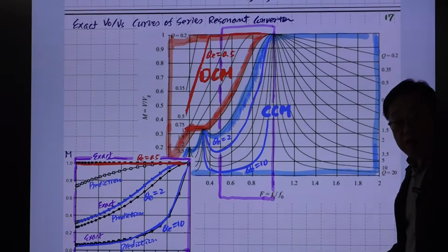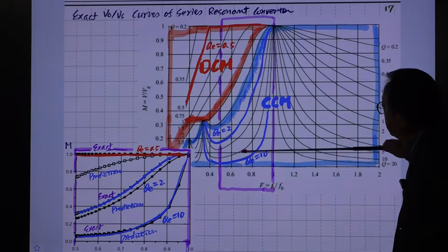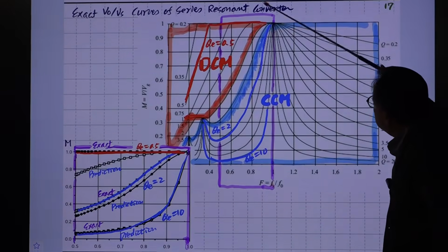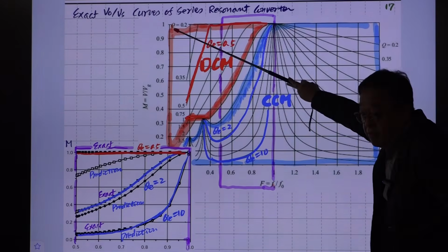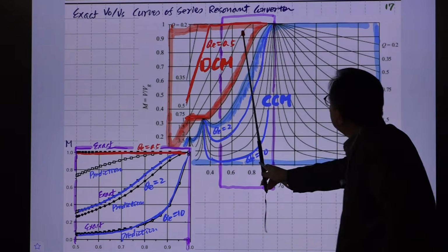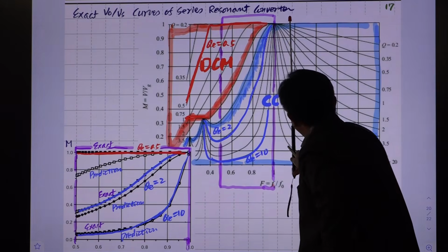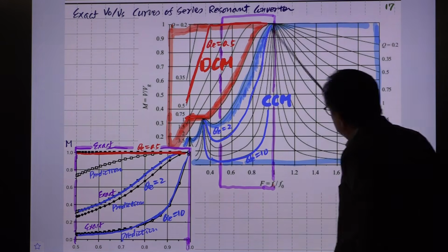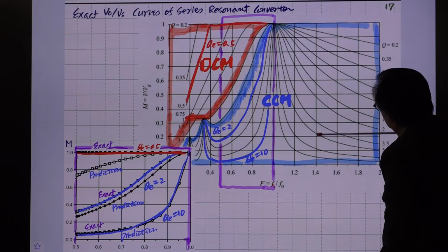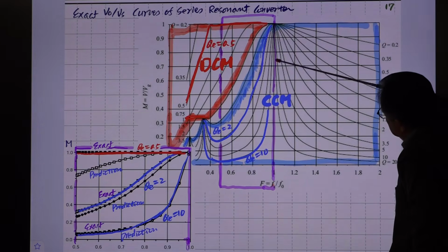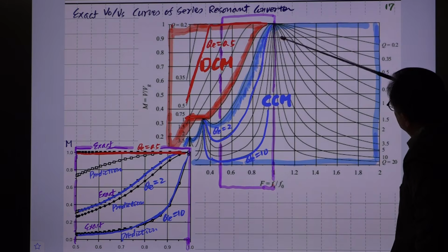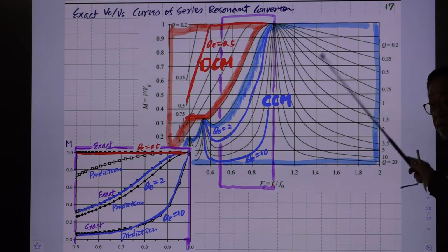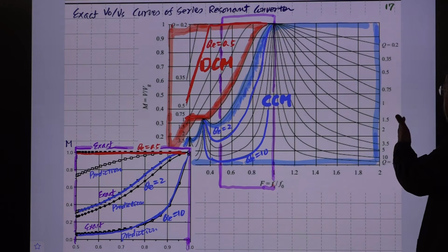This is a gain curve. This represents the gain from DC in to DC out, and at this frequency it is 1, right? At this frequency, this is above the resonant frequency, but it shows very systematic behavior. This looks like resonance with different Q. So this one is okay for above the resonant frequency.